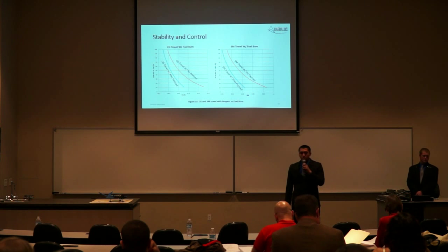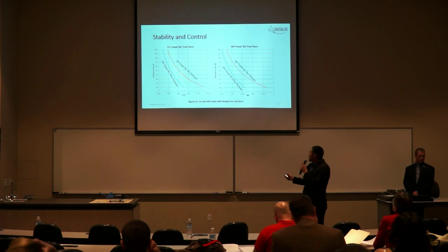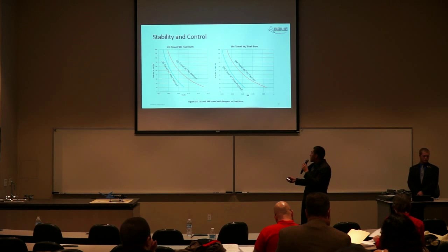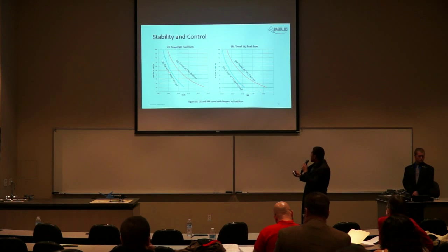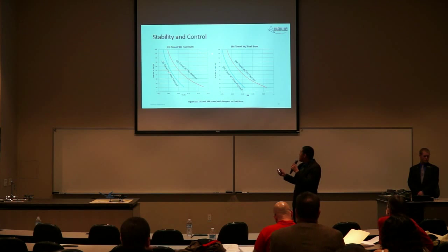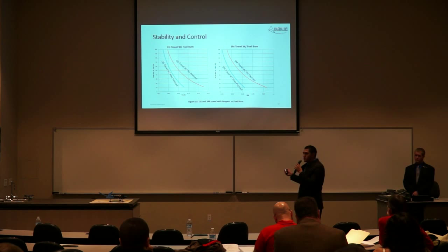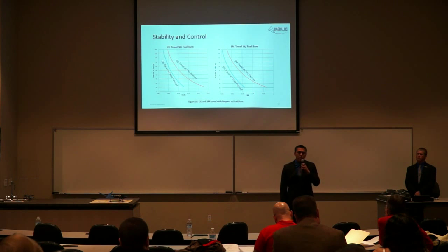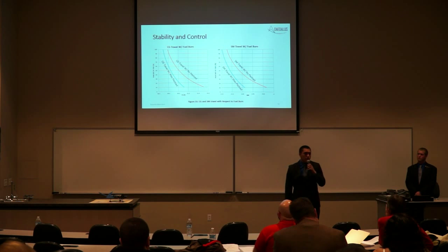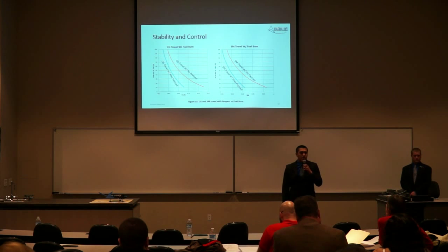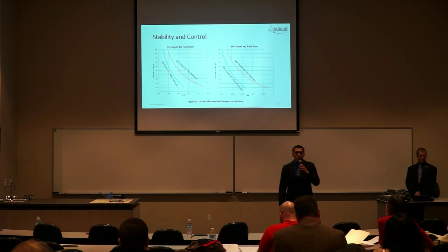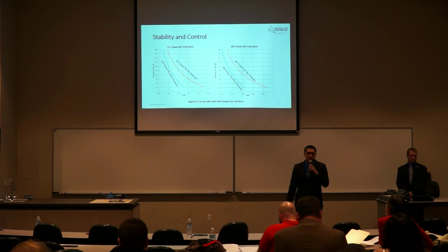When taking into consideration fuel burn on the left, you can see the large change in CG travel due to the fuel for both no payload and max payload. This corresponds to the large SM travel as well, starting from 100% of fuel capacity down to 10%, which corresponds to a 2% static margin. This means that the YB-3 becomes extremely maneuverable during flight while burning fuel. However, the YB-3 is still statically stable, since an aircraft is considered stable when the static margin is above 0.